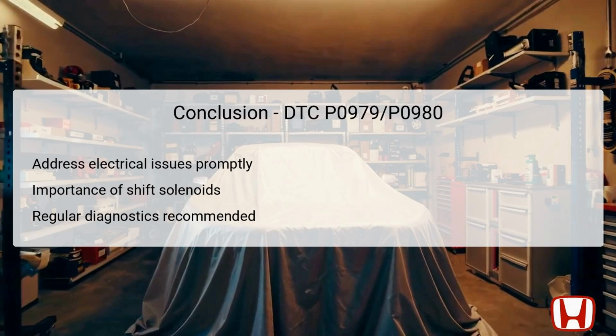In conclusion, addressing issues related to DTC P0979 and P0980 promptly helps maintain optimal performance of the Honda Pilot's transmission. Understanding the pivotal role of shift solenoid valve C in smooth gear transitions underscores the importance of timely diagnostic and repair actions. The electrical nature of these faults emphasizes the need for careful inspection of circuits and wiring, rather than mechanical transmission problems. Regular diagnostics and preventive maintenance can be instrumental in preempting future DTC codes and ensuring the longevity of the vehicle.